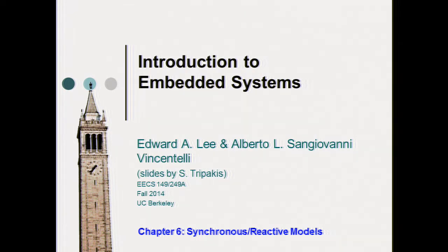So you have two options, right? One option is analyze to death, so simulation, simulation, simulation. But again, the confidence of the result depends on how many simulation vectors you tried, and so how well you visited the input space. And so there is no guarantee that if the simulation result tells you that the circuit is okay, it is really okay.